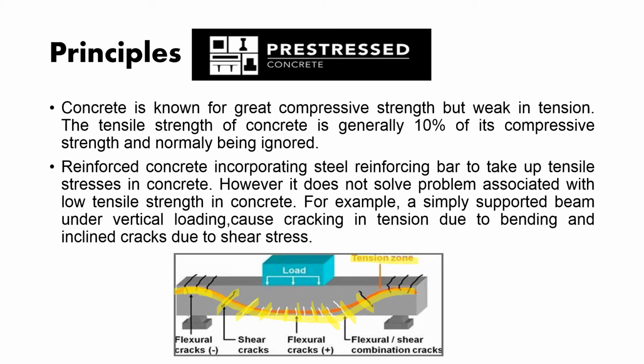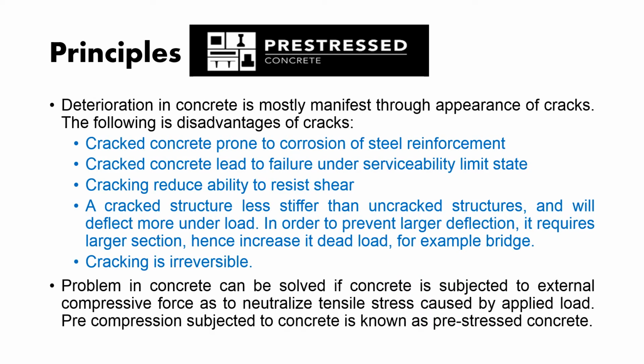So how to prevent this crack? By using prestressed concrete, we can reduce it. Deterioration in concrete is mostly manifested through the appearance of cracks. So the following are the disadvantages of cracks. First, cracked concrete is prone to corrosion of steel reinforcement. Once concrete cracks, the reinforcement inside will be exposed to the outside, so it will cause corrosion over time. Cracked concrete leads to failure under the serviceability limit state. Once it cracks, the strength is reduced, so it might fail.